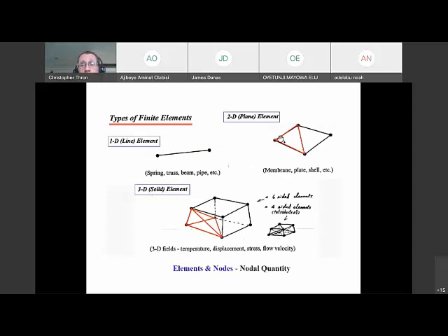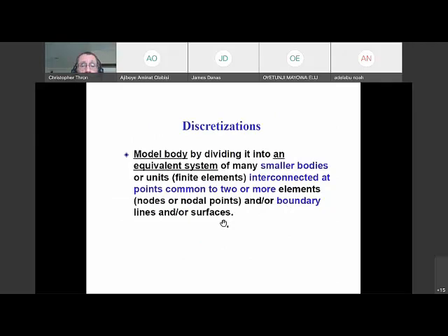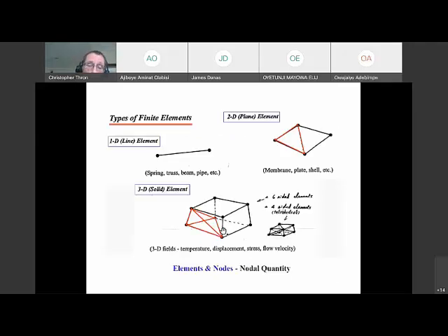So here are some examples of elements. Here's a triangular element, as I mentioned. In 3 dimensions, you would not have a triangle. You'd have this, which you would call a tetrahedron. You see the red here is a tetrahedron. You can also do higher dimensions, then it's called a simplex. So a triangle is a 2-dimensional simplex. A tetrahedron is a 3-dimensional simplex, and higher dimensions would also be simplexes. And you can see the simplex consists of edges and nodes. The nodes will be very important because we use the nodes to define function values.